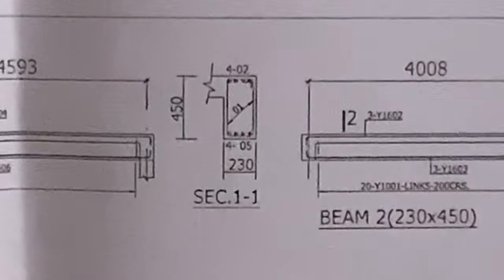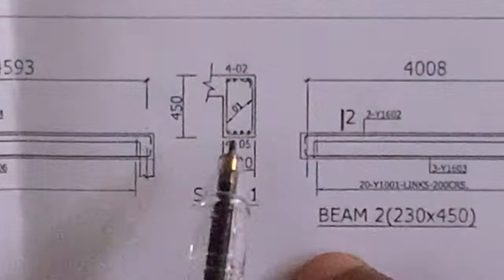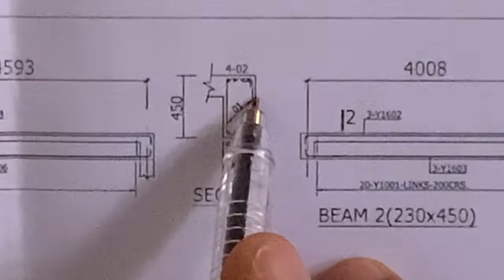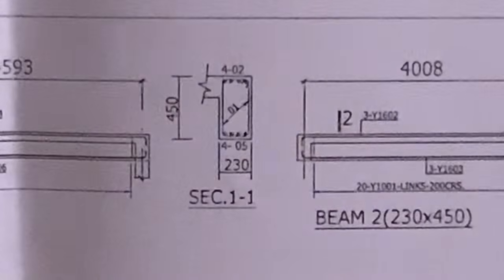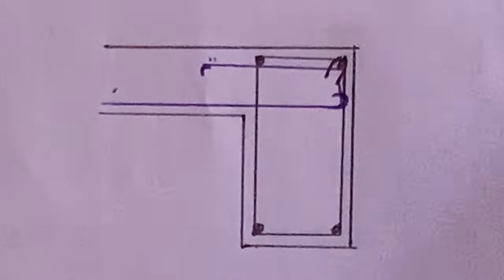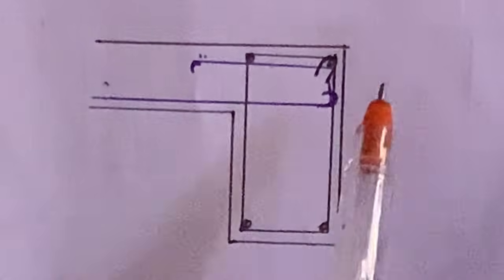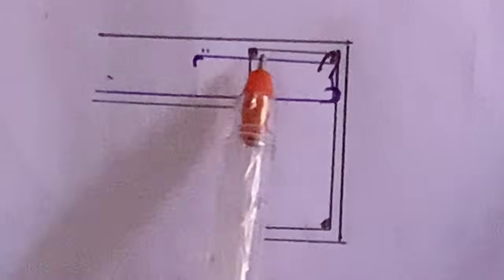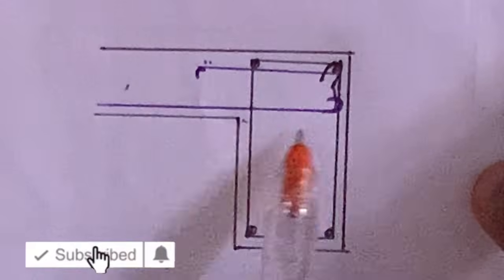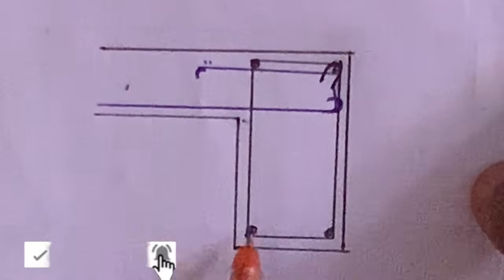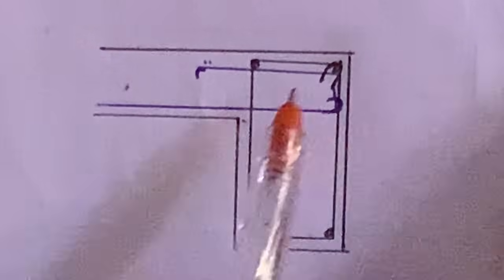So now, when you are measuring for the concrete, what you do is that you will cut this concrete like this. I don't want to draw on this paper, so let me just make a caricature drawing. Okay, so now let's just say this is a caricature drawing of our beam and slab. So this is our beam, right? This is our suspended floor attached to it. Because as you can see, the reinforcement for the slab is entering the reinforcement for the beams.